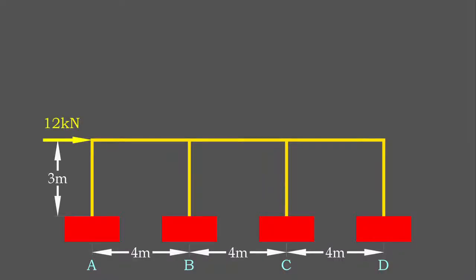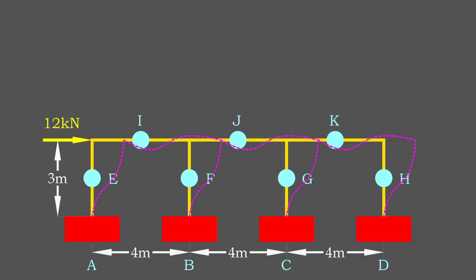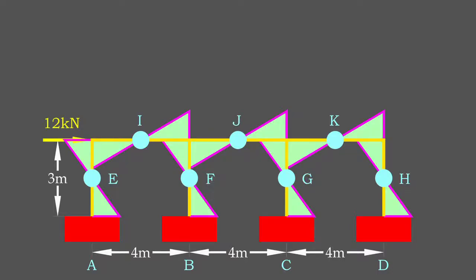A statically indeterminate frame, such as one with a fixed base, can be analyzed as a portal frame when subjected to lateral load. The behavior of a portal frame is governed by hinges that indicate the points of inflexion for the deformation curve. Those points are placed at the center of the column and girder, where the bending moment is assumed zero.